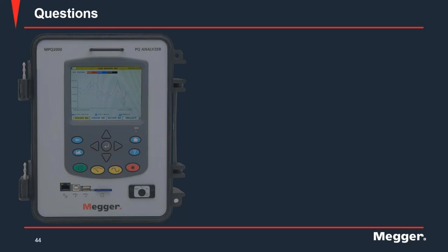That would indicate that this problem can either be from a faulty rectifier somewhere else in the system, but you also say with the loads off, you're not seeing it. So this really seems to indicate that this is a harmonic issue. That's most likely the cause of it. Even in here, it's mentioned that if you are using a filter, it does help somewhat. So you may want to try putting a line reactor in there to see if you can block some of the harmonics. But the ideal thing that I would recommend is hooking up an analyzer there and taking a recording of the harmonics. Look at both the input to the rectifier and the output of that rectifier to get an idea of what level those harmonics are at and what frequencies they're at, so we can get the proper filtering on them. Of course, that does seem to be the most likely cause of the problem.